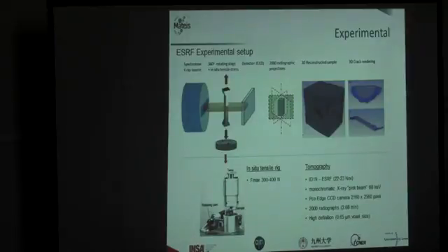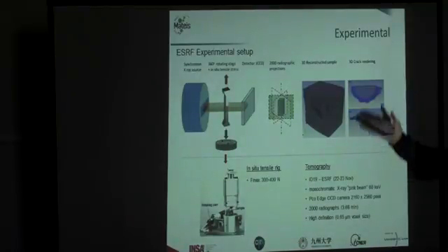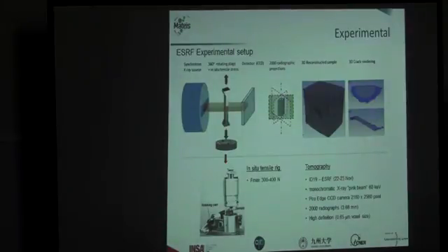With this specimen, we pull in order to open the crack, and we obtain 2000 radiographic projections, and then we obtain the 3D shape of these cracks. Regarding the tomography experiment, we were working with 60 keV, and the voxel size was 0.7 microns. High resolution.